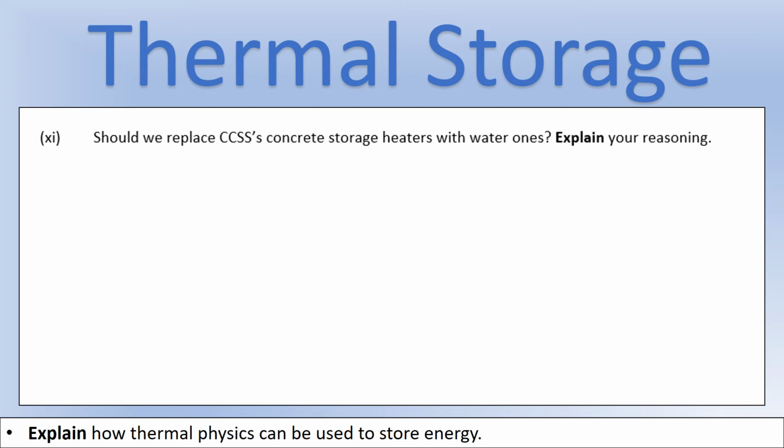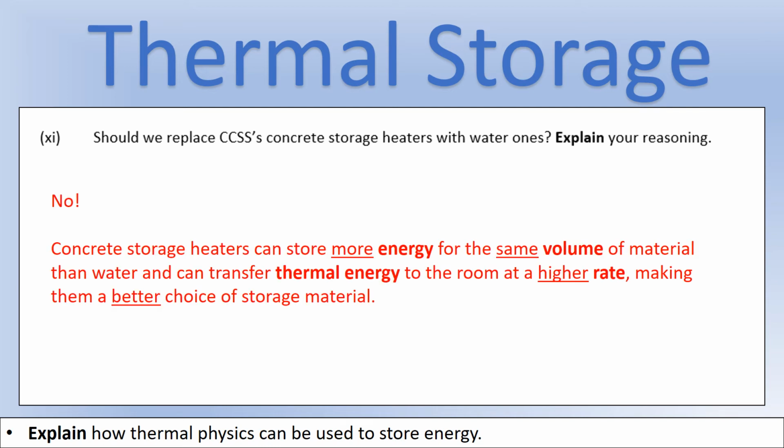Okay, so let's have a look at my reasons. I picked two key things in terms of explaining this. One, concrete can store more energy for the same volume of material than water, which we already saw earlier, and two, it can also transfer it to the room at a higher rate. Those are the two reasons why I think we should pick concrete heaters rather than water.